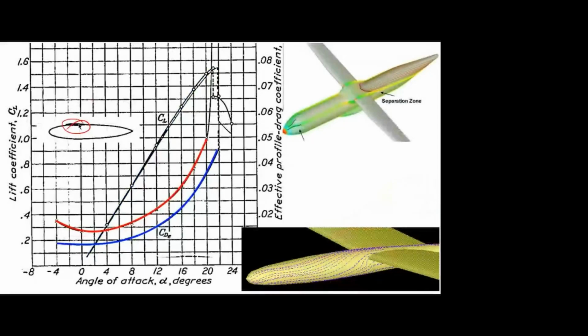So only one parameter. Always we have to be careful that the flow should not be disturbed on the upper surface. Okay, if you take the lower surface, it will be a high pressure region. Even if you disturb it, we can compensate. But on the upper surface, most of the flow changes occur, and we have to get the maximum acceleration and low pressure region. So the upper surface flow should not be disturbed. That is the main thing.